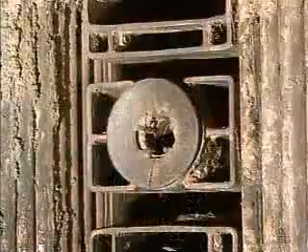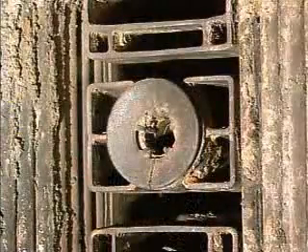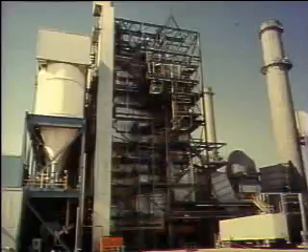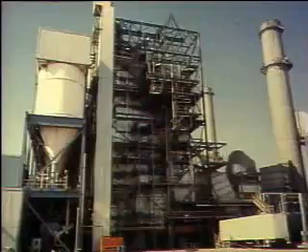The burners that supply the fuel to the furnace are usually located either in the corners or on the sides of the furnace. These burners are designed to burn coal. If your plant uses oil or natural gas, the burners will be somewhat different. Now that we've seen where combustion takes place, let's turn our attention to the requirements for combustion. A boiler needs a continuous flow of fuel and air in order to maintain the fire in the furnace. Let's look at a typical boiler and see how fuel and air are supplied.